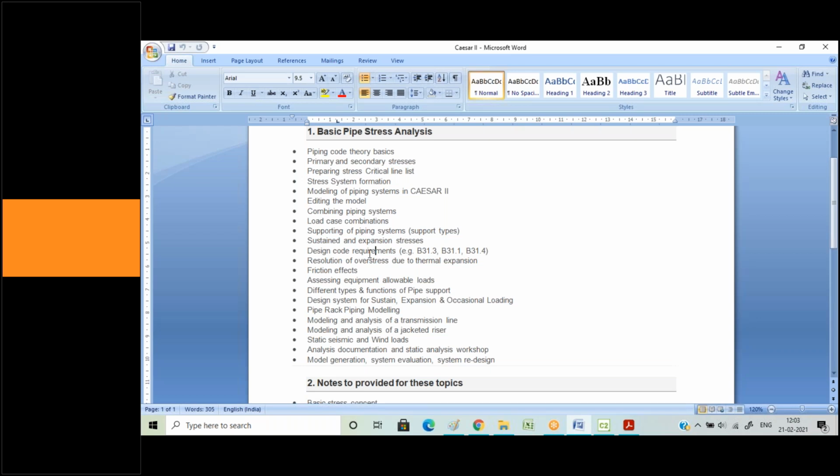So the answer to this is very simple. This is basically your allowables, the allowables that have been defined for these B31.3, B31.4, B31.8 different codes. Okay, they all are different. The allowables change with the type of code that we're using.